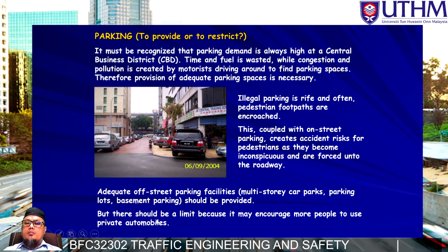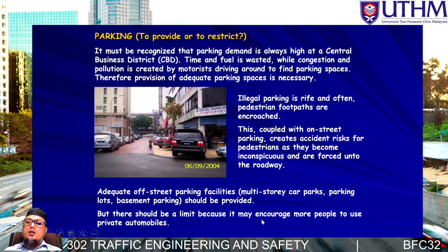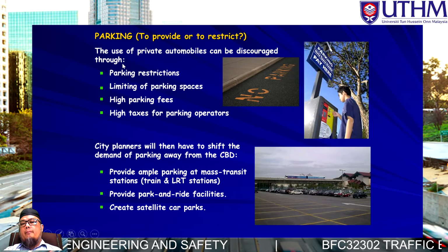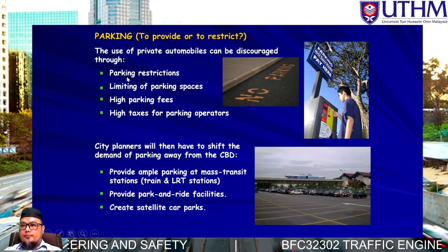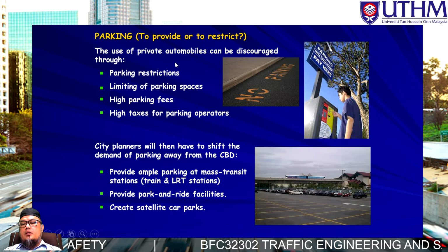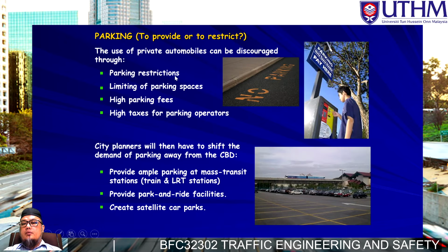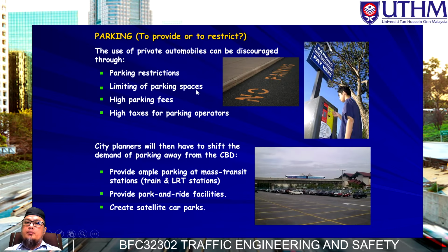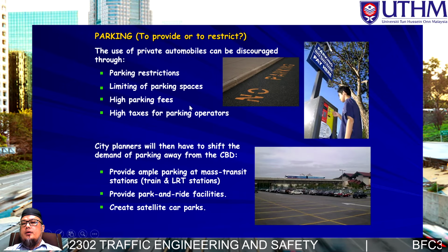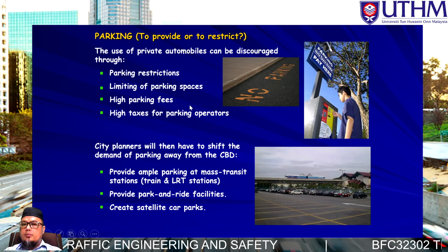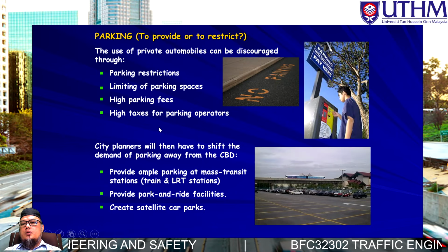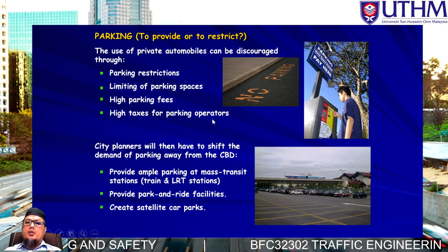Okay, but there is some limitation, because providing parking may encourage people or drivers to use private automobiles. Okay, this is the behavior of the driver. The use of private vehicles can be discouraged if we do some restriction of the parking. We just limit the number of parking lots or parking spaces, and we charge higher fees for using that particular parking lot or parking area. Also impose some high tax for the parking operators.